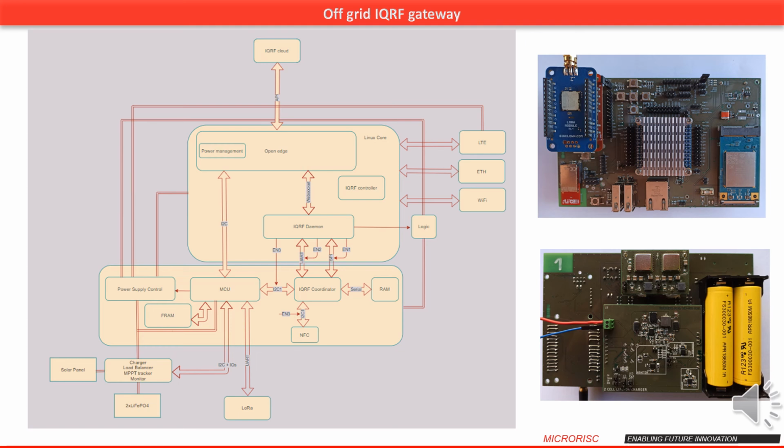From a software perspective, in addition to Iqrf Gateway Daemon and Iqrf Web Application, the gateway is complemented by two additional software modules. First module is dedicated to communication cycle timing, which performs a controlled shutdown of the Linux machine and subsequent setup of the circuitry responsible for voltage control, including timing and subsequent wake-up of the hardware. The second module is responsible for the native connection of the Iqrf gateway to the Iqrf cloud, which is also part of the whole project.